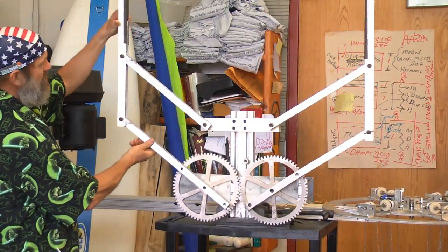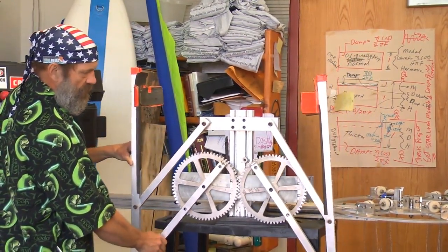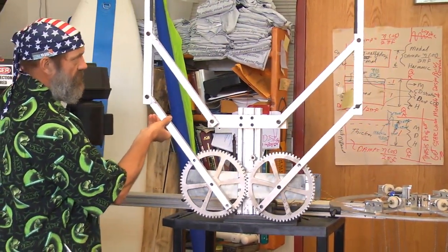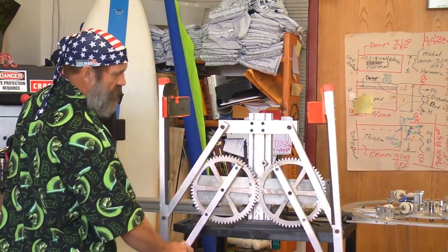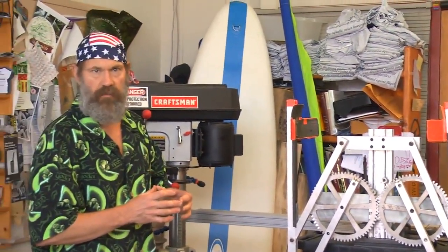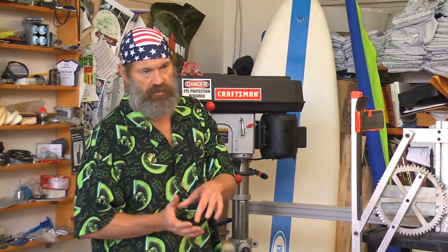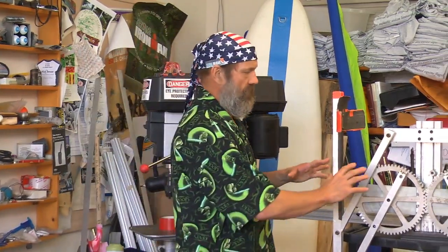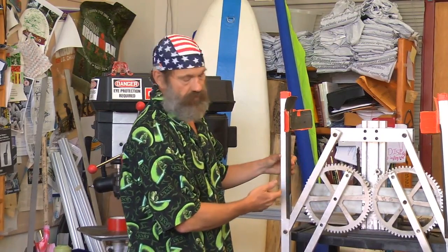And notice how the 4-bar linkage is driven by the two main gears. So it maintains synchronization between the two arms. So gears not only are used as transmissions in terms of reducing the speed and increasing the torque of a motor that's input to the system, and then providing a slower speed, higher torque output, gears can actually be used as part of linkages to accomplish a motion function.